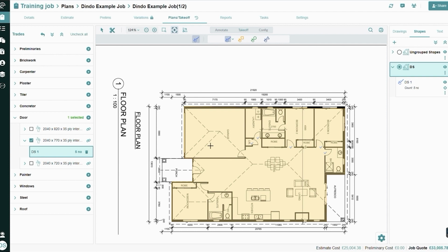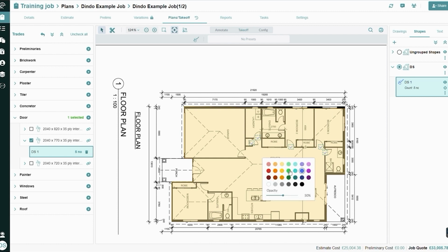Okay, so what I was talking about there is editing shapes. You have the ability to edit shapes as well. So editing a count is removing one that you put in by accident, or editing a shape is moving a corner. For example, this corner top right here looks a bit off to me, so let's fix that. So we'll go and click select on the button bar, top left, and you can do a couple of things. You can click on the shape over here on the right, and you'll start to get some edit tools. So you can change the color. I could change the color of the ticks, if I wanted to, or I could delete them as well, as another way of doing it.